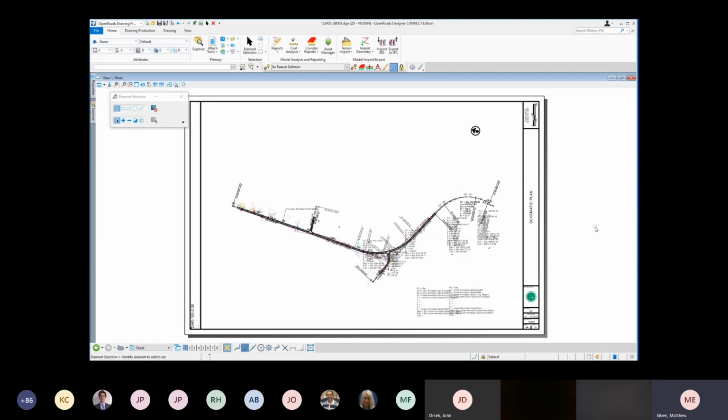And that design model is going to be used, where we're going to place our name boundaries, and it's also going to sort of serve as what we're going to call our container file. Then the name boundary process will create the drawing and sheet models and place them in the same DGN file. And most of our view display will be handled within that design model and will be carried through with live nesting into the other models.